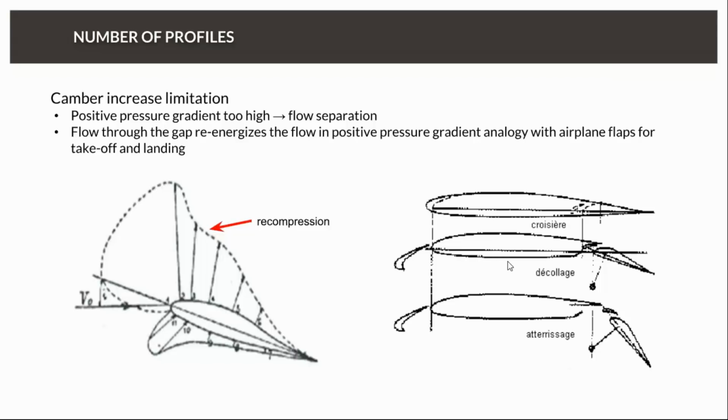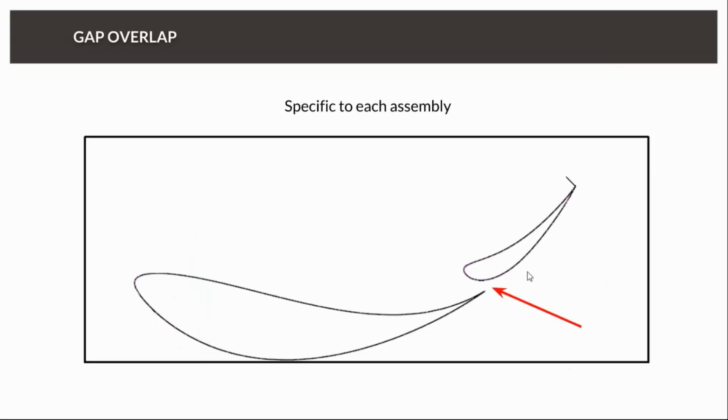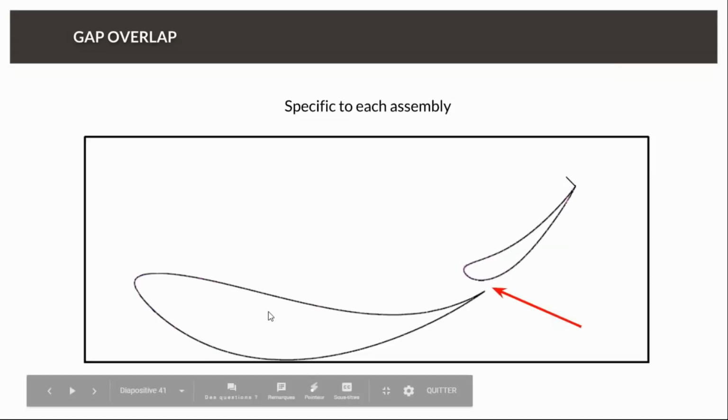And the downforce coefficient, or in the case of the plane, a lift coefficient, as the main plane cannot be curved more, we will create curvature and chord by creating a flap opening and a leading edge slot, so that the flow passing through the slot helps the boundary layer to stay attached. And in the same way, we will have the same phenomena for our